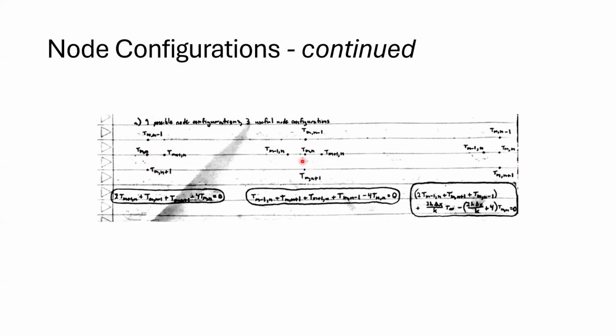us if we'd like. What is important to note here is that this left side configuration actually has the exact same equation as the right side here, except for the fact that this right side has convection. And in table 4.2, you'll actually see a little superscript with a note that says that you can just set these convection coefficient terms equal to zero, and you'll end up with the proper equation for an adiabatic boundary condition. And that's given over here on the left side.